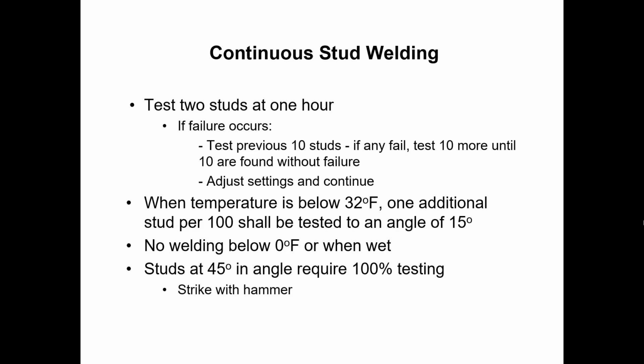Just to step back and make sure we understand what's required here. You're testing two studs at the startup, visually, doing a bend test to 30 degrees at startup. You're doing the same thing every hour. If it's really cold, so below 32 degrees, you've got to test one additional stud, and this is a quantity trigger versus a time trigger. So one additional stud for every 100 studs needs to be tested to an angle of 15 degrees.